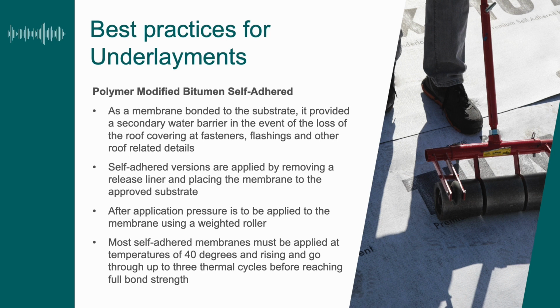Because they're bonded to the substrate, when the roofer is walking on it while installing the roofing system, it doesn't really move that much around the fasteners. It does not create an opening around the fastener head, so it actually helps with that versus a mechanically attached system.